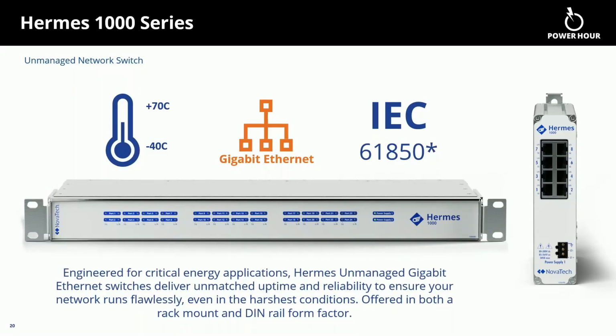It still operates on layer 2, but it's an unmanaged IEC 61850 gigabit switch. Now that's a lot of words to say. You just plug this thing in, it's plug and play, and it works. But also you can beat the absolute tar out of it because it's a 61850-3 certified switch. So that is a standard for substation hardening that has some high bars to clear.